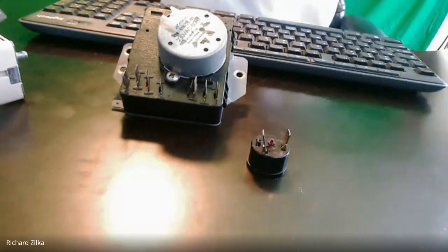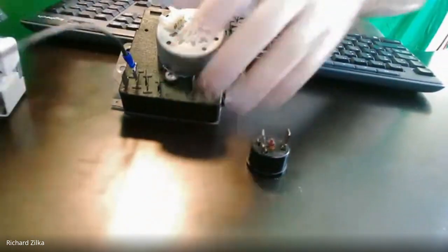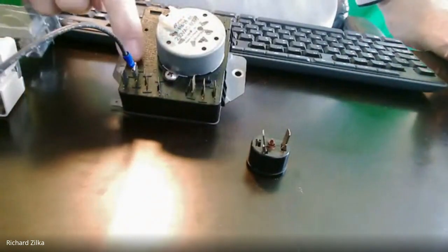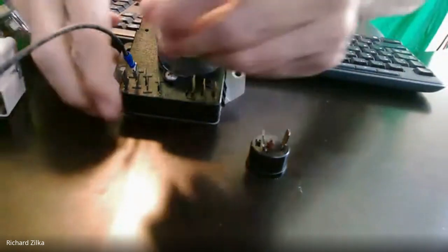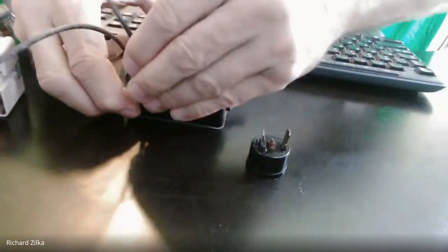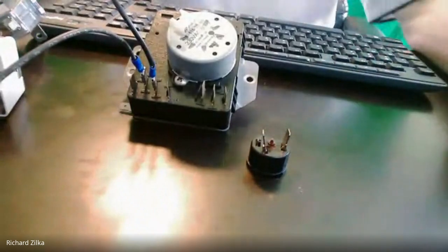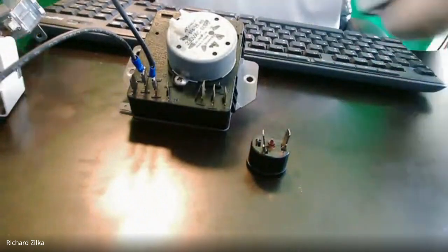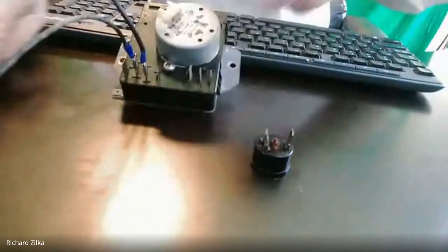In the timer, we have to bring power into the timer. So we connect a wire with power coming in, for example, and it goes in here to a switch, and it's going to come out the timer. Let's just say here, to turn the heater on. Now that's all good, because what does the timer do? The timer runs and it's set for a specific time, 20 minutes, 30 minutes, or whatever. And then the timer times out, that switch opens, the heater cuts off.